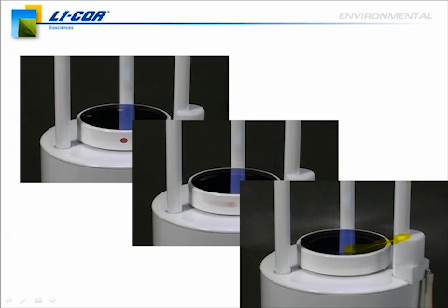So if you are making eddy covariance measurements, you obviously don't want this to happen in the middle of your 30-minute averages. So you can set this up to only check and clean itself as needed between your 30-minute measurement averages.